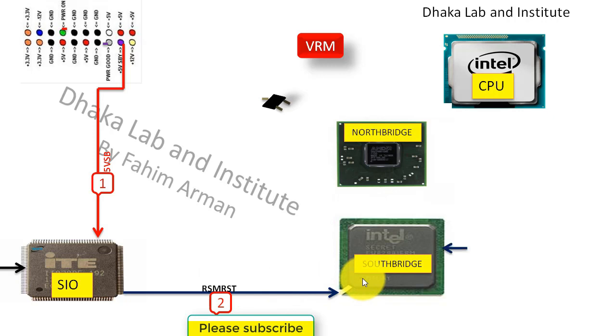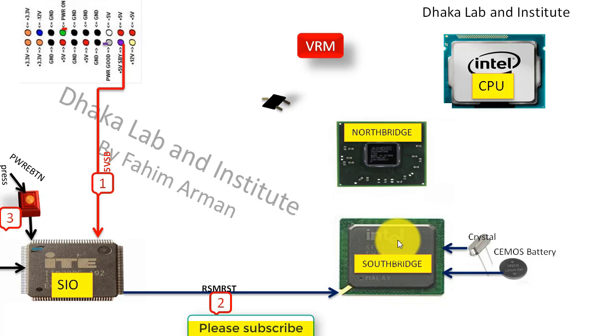The South Bridge also gets crystal frequency if the crystal is okay and provides frequency, and if the CMOS battery passes voltage and the RTC section is okay, then the South Bridge is confirmed okay.